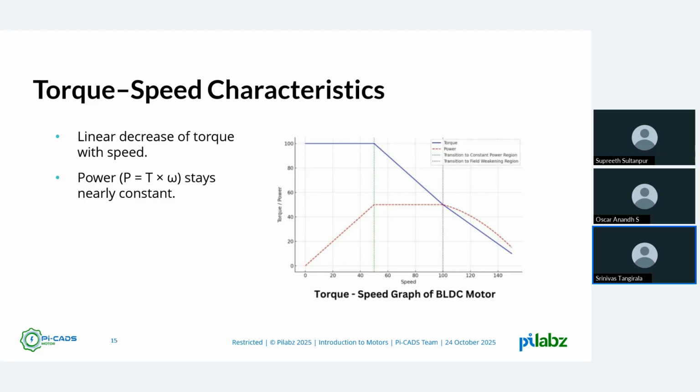The torque is measured in Newton meter. So the operating point is a combination of these two values. In the continuous operating mode, there will be one particular torque and speed value. So if we can determine this envelope graph, we can safely determine the peak operating points and the continuous operating points of the motor.